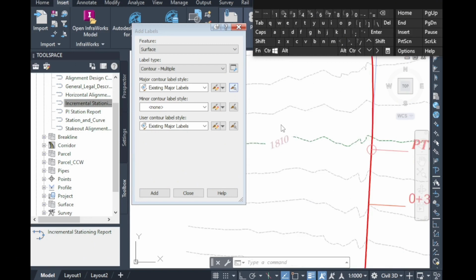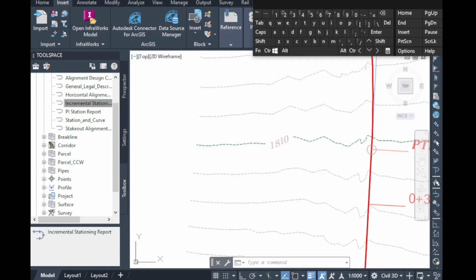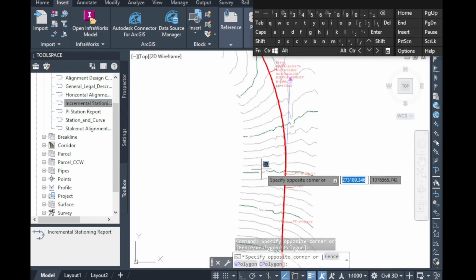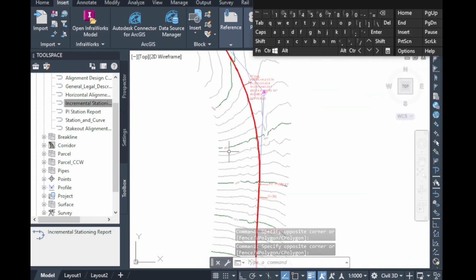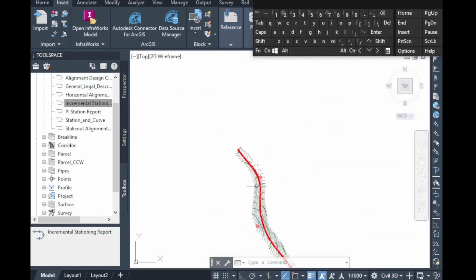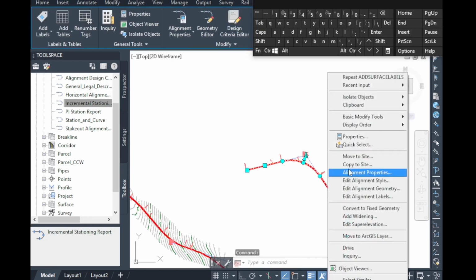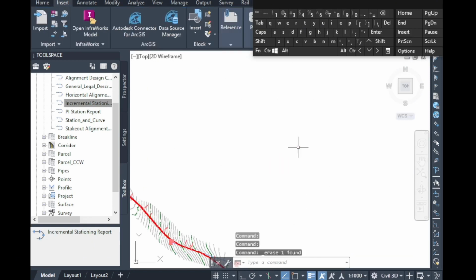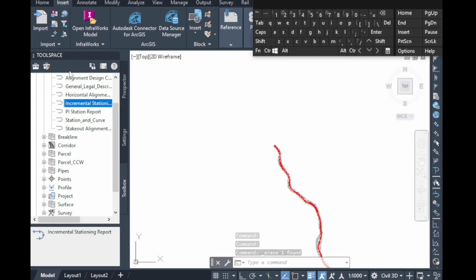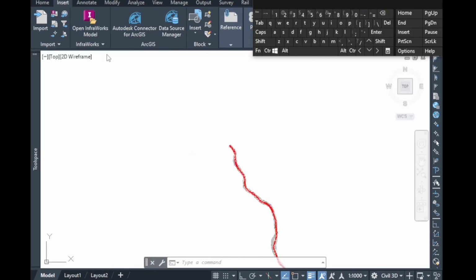It's okay now, but you can choose your style. The other thing you have to know is you can hide and unhide the tool space by simply clicking it. It is visible when your cursor is close to it and hidden when your cursor is far from it, and it also works for the Properties tool.